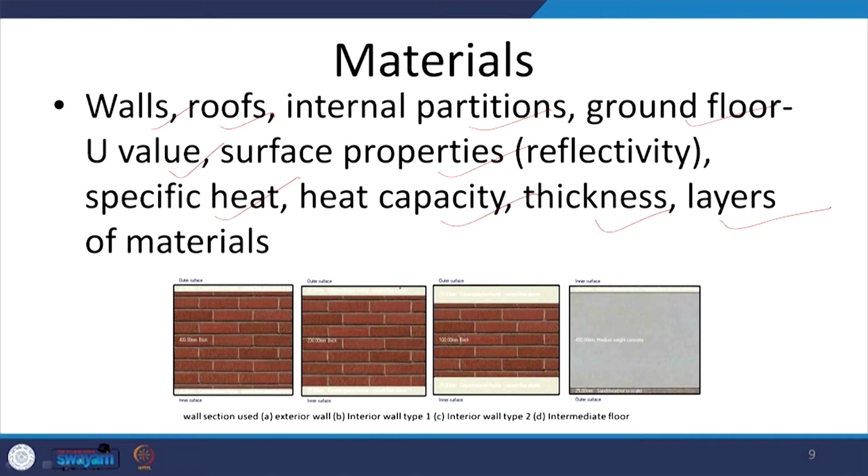So, this is the regular brick wall, which is 230 mm thick brick wall with 25 mm of internal plaster and 25 mm of external plaster which is added to it. A software like Design Builder and almost all others already have the thermal properties of these individual materials inbuilt into the software. Here it is for concrete.